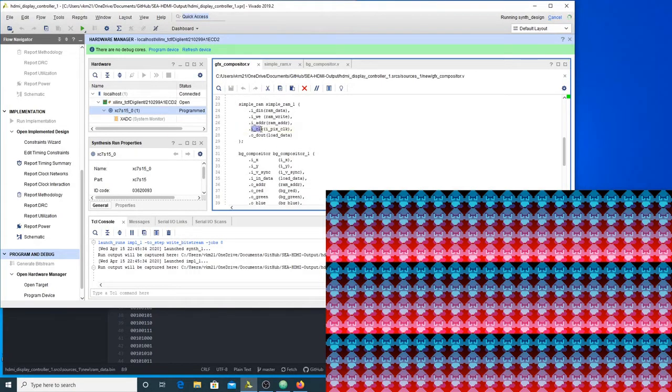And yeah, for the clock for our RAM, theoretically we could run it faster, but I figure it's kind of fun to just run it on the same clock that we're using for all our graphics system, which is all based on the pixel. So later, if we need to load more data, we can move to a 16-bit memory architecture, or we can load the appropriate bytes in advance and store it in a register, to build our pipeline for doing all our graphics processing.